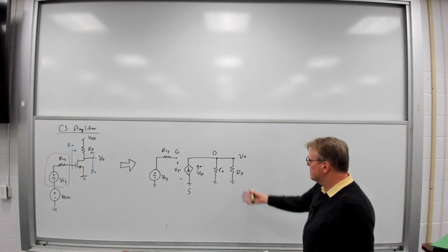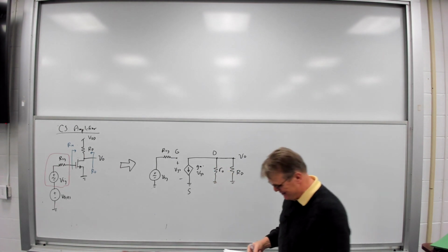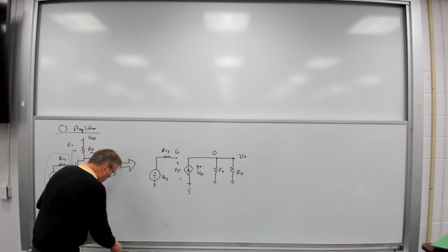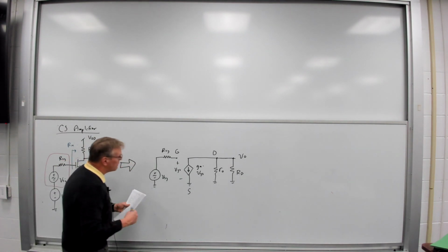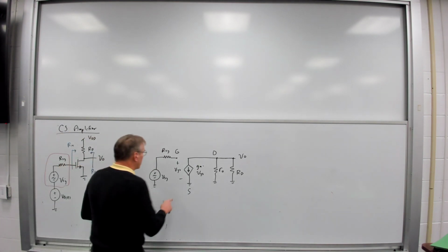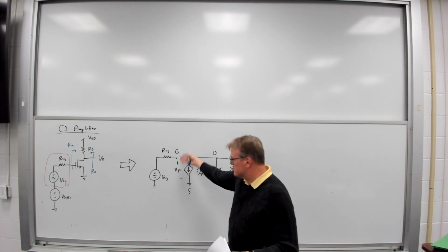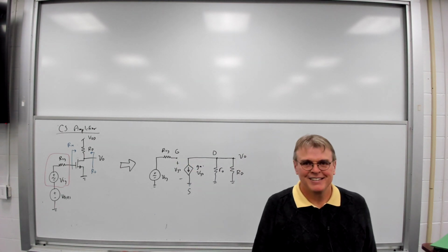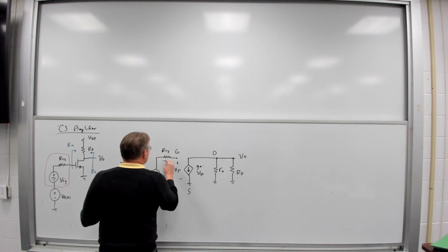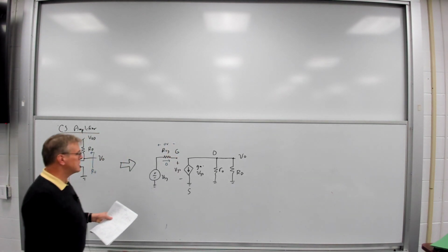So in this case, we actually did this circuit last week, right? We actually went ahead and analyzed this. The difference between this week and last week was that resistor. But let me ask you guys a question. What's the small signal AC current flowing through that resistor from that diagram? 0, yeah, it's an open circuit, right? The gate's an open circuit. So this is 0, which means I have 0 volts across R_sig.